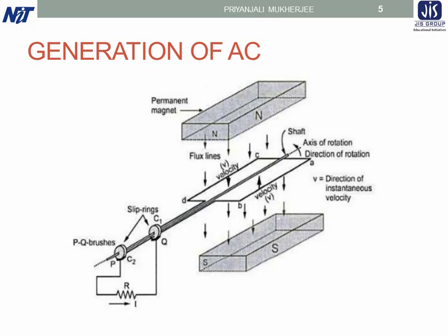So why do we generate electrical energy in the form of alternating current? Because the AC generator has no commutator and can therefore be built in very large units to run at high speed, which produces high voltages, almost 33 kV.